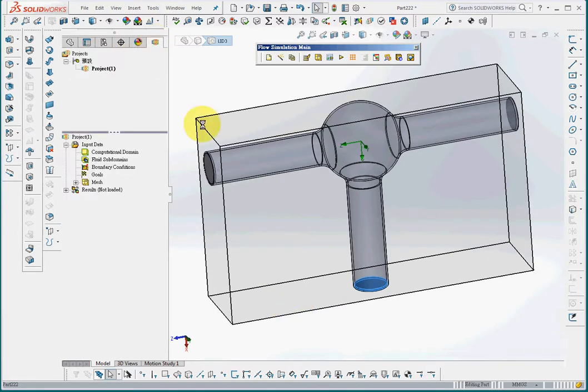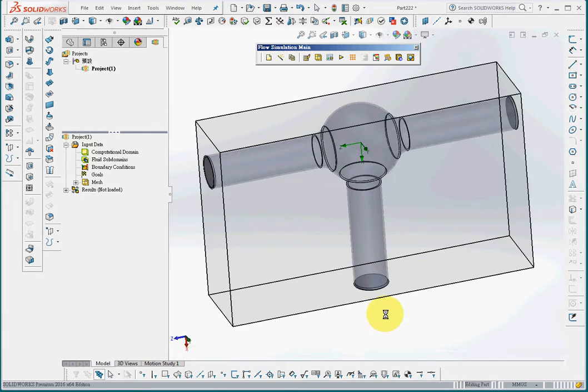And now we go back to flow simulation, and we have finished with the first step of flow simulation, which is drawing a 3D model, creating a project, and defining the covers or the lids to define the boundaries. And the second step, initial condition, will be implemented by the wizard.